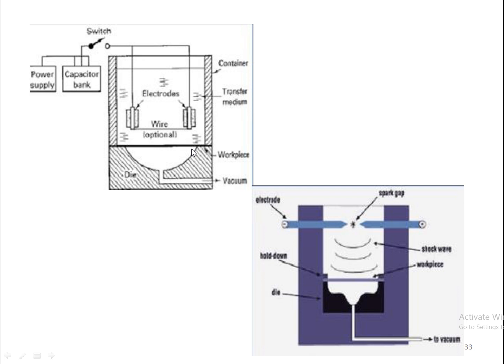Now one of the advantage or the disadvantage, depending upon the application, is that with this, it will not get converted in a single shot. The energy produced by this spark is less compared to what is produced by the explosive forming. So multiple sparks need to be generated to produce the final shape, depending upon the shape. In a way you can adjust the spark, and in a way you can adjust the process as well. Since it is not happening in a shot, you can adjust the entire process. Right. So you'll get a better idea with the second diagram.